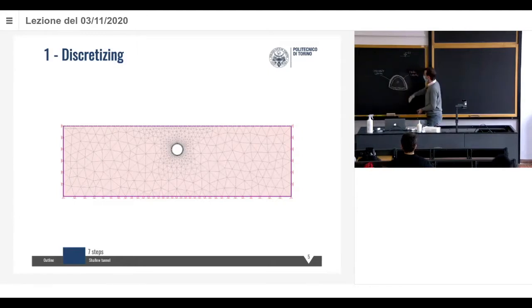Right? So we have a ground surface up here. Let's consider that this is a deep tunnel. How do we define a deep tunnel with respect to a shallow tunnel? Those that went through the tunneling course or rock mechanics, that you've seen this. How do you define a deep tunnel with respect to a shallow tunnel? The number of diameters we have here. That's right. Okay, if they are more than 2, we say it's a deep tunnel. Normally we say like that.